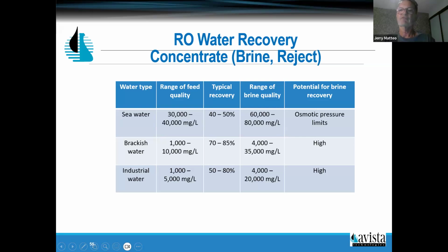in quantity of permeate. Seawater we know is really high conductivity, and here they're expressing as milligrams per liter. It's mostly sodium chloride or salt. Freshwater, oh, we've got industrial here. So freshwater can be much lower. They're showing it up to about 10,000. And the industrial water can be all over the map because we can use RO to recover fresh water out of treated industrial water too.